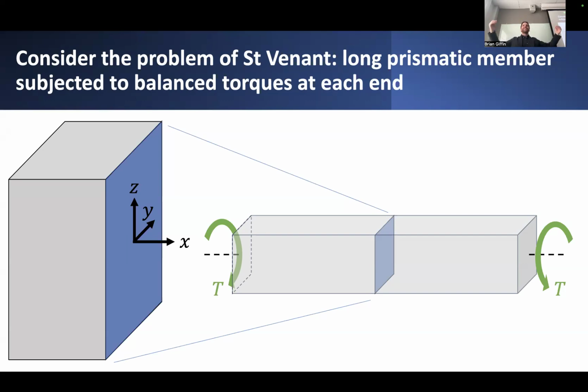It might be bending loading, it might be axial loading, it might be torsional, twisting loading, as we'll consider momentarily. But if this member is relatively long, then you can apply Saint Venant's principle to say that if I don't really care what's happening far away at the ends, wherever I'm applying these end loads, then it suffices to just look at what's happening at a section of